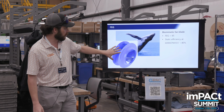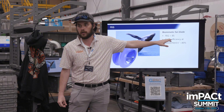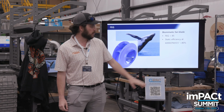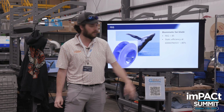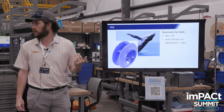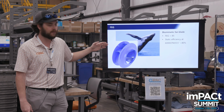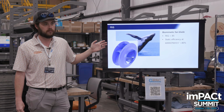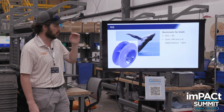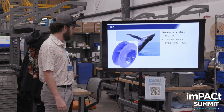But anyways, this wheel has a really high FEG score. 85 is like the highest I've ever seen. Really high FEG score. But if you apply it in the wrong spot, like 6,000 CFM at half inch static, for example, that efficiency is going to be less than 40%, which is not good at all. So that's why FEG has kind of been phased out, because it really depends on how you're applying those. We're just talking about purely the maximum efficiency it could ever be with FEG.